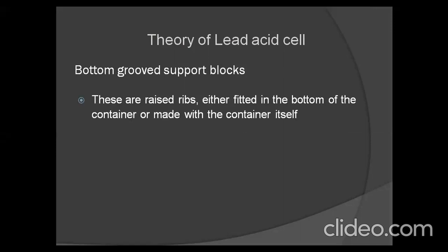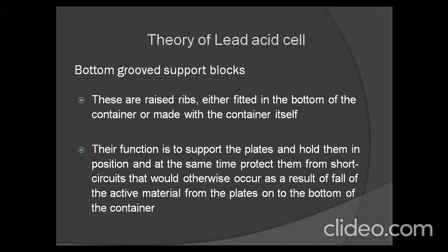Bottom grooved support blocks. These are raised ribs either fitted in the bottom of the container or made with container itself. Bottom grooved function is to support the plates and hold them in position, and at the same time protect them from short circuits that would otherwise occur as a result of fall of the active material from the plates onto the bottom of the container.